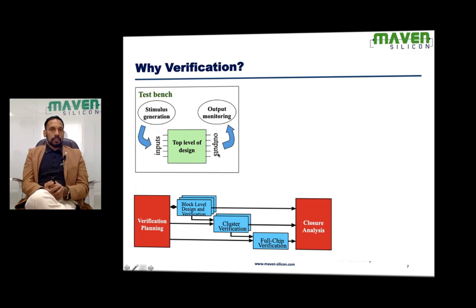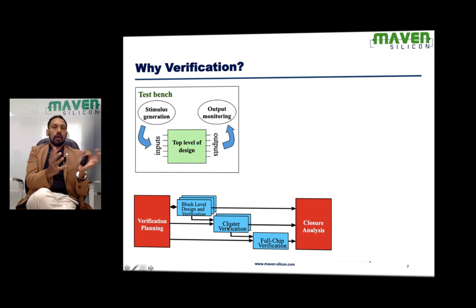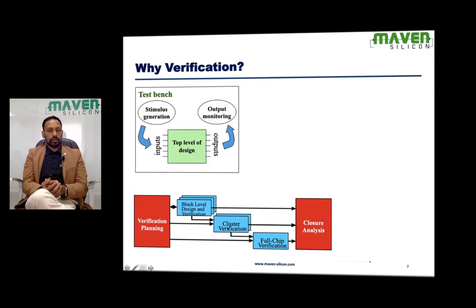To run simulation, we need to come up with a detailed verification plan. If we are going to deal with different things like block level verification or subsystem level verification or chip level verification, then we need to identify the right verification methodology. For block level verification, we prefer white box verification. When it comes to chip level verification, we prefer black box verification. But when it comes to subsystem, we go with gray box verification. Gray box is nothing but the combination of white box and black box.